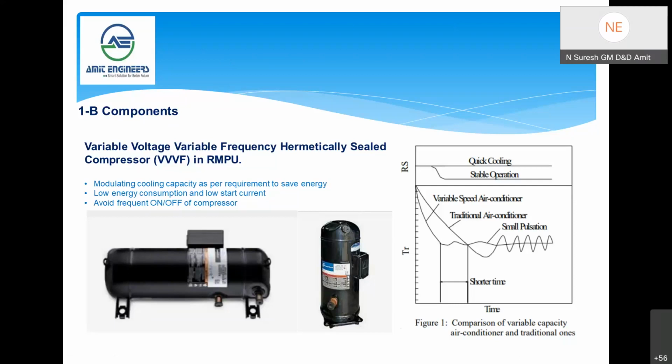And one last thing: is this triple VF technology not employed in other compressors in Indian Railways, or is it for the first time that this technology is used in compressors? Yes, sir. So far, LHB has been launched more than 15 years, and so far fixed compressors are being used. Since the compressor manufacturer recently developed a suitable variable frequency compressor for transport application, that's how we are taking the benefit to save the energy. This is the first time.